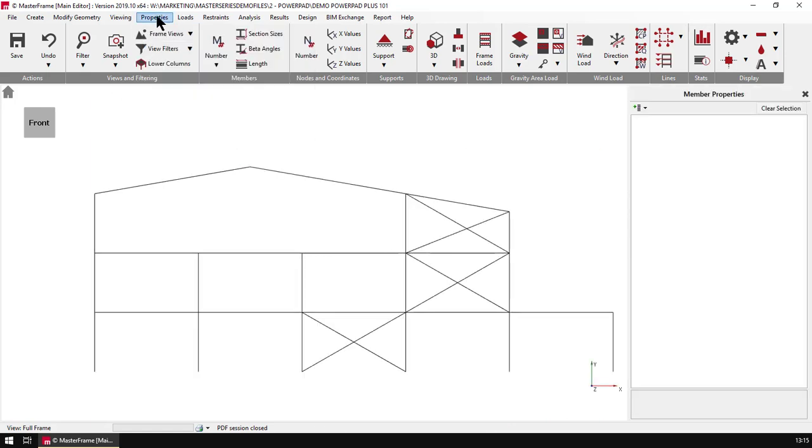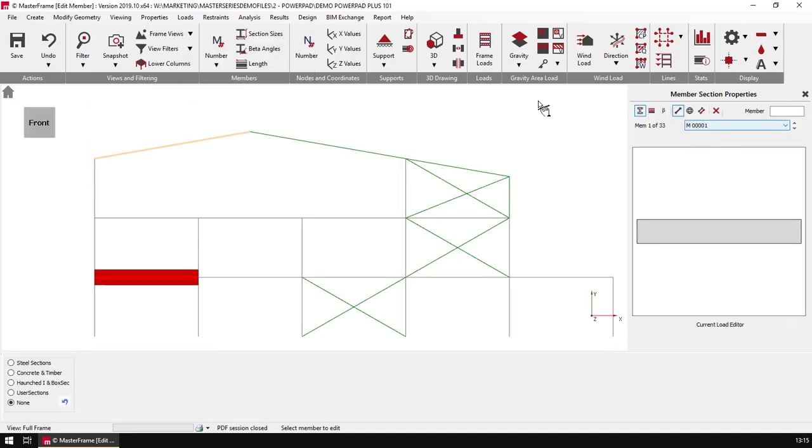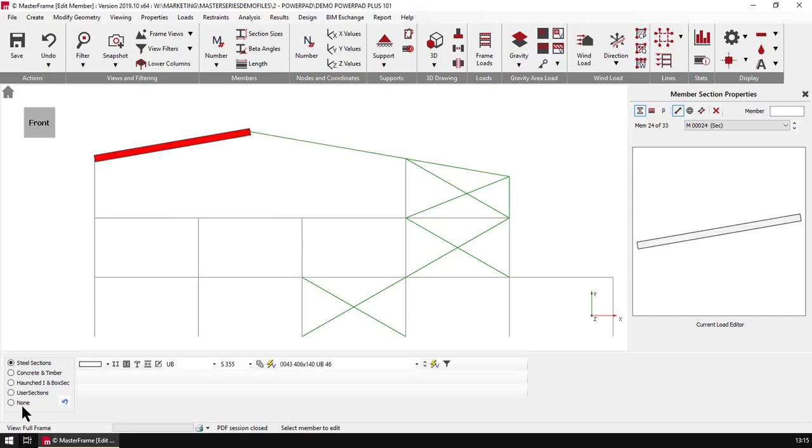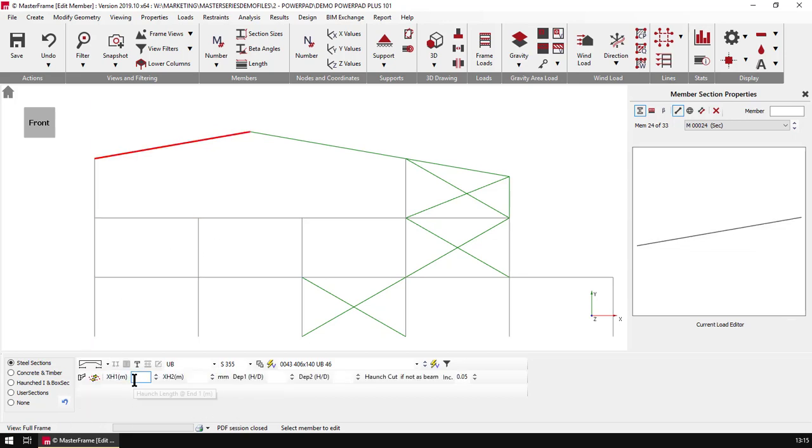You also have all your properties of materials. We saw the basic definition of steel. Some of the members were already defined. We can turn around and say, well, actually I want that to be a double haunched member, and I want it to have a 1.5 meter haunch and a 0.75, both the haunched areas to be twice the root, and there we get our section defined out of the 457 that we chose as our initial section size.